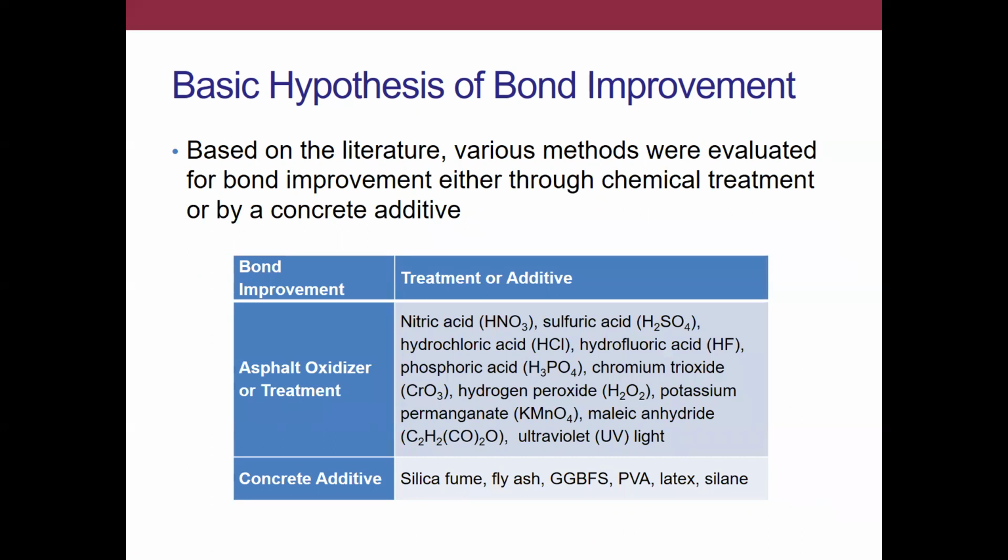We also compared the effects of silica fume and some other additives, because those are known to improve chemical bonding or the ITZ properties in concrete with virgin aggregates. But here we did not find much improvement with RAP. So I will not really be discussing those concrete additives at the bottom. Instead, I will be focusing here on